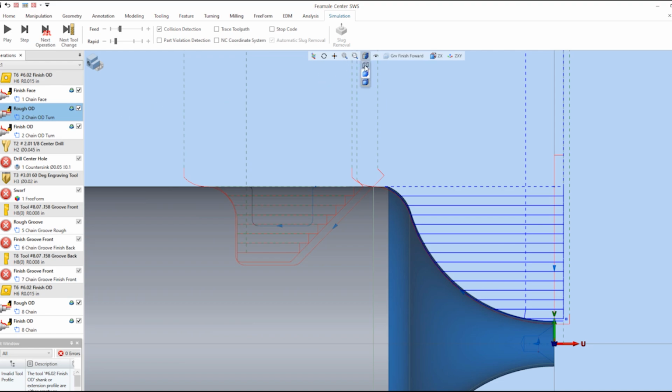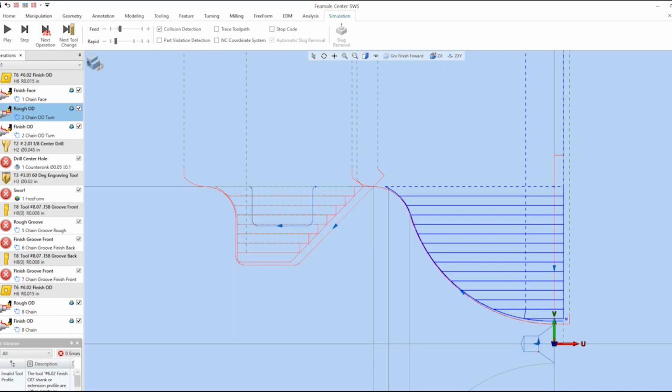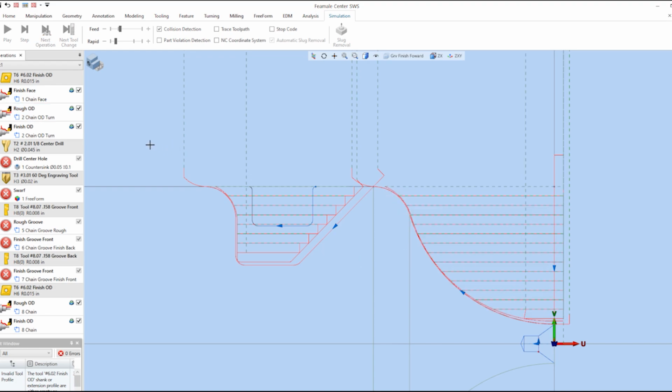Let me actually hide the stock. So here, and you can see how, man, every time I do a video, that guy starts that grinder. I hope you can hear me okay. But you see how the roughing cycle put the tool very close in the Z direction, and the X is standing away a little bit because I have some stock allowance. And then I have the finish cut of that profile program with tip compensation on it. You see here how it looks.